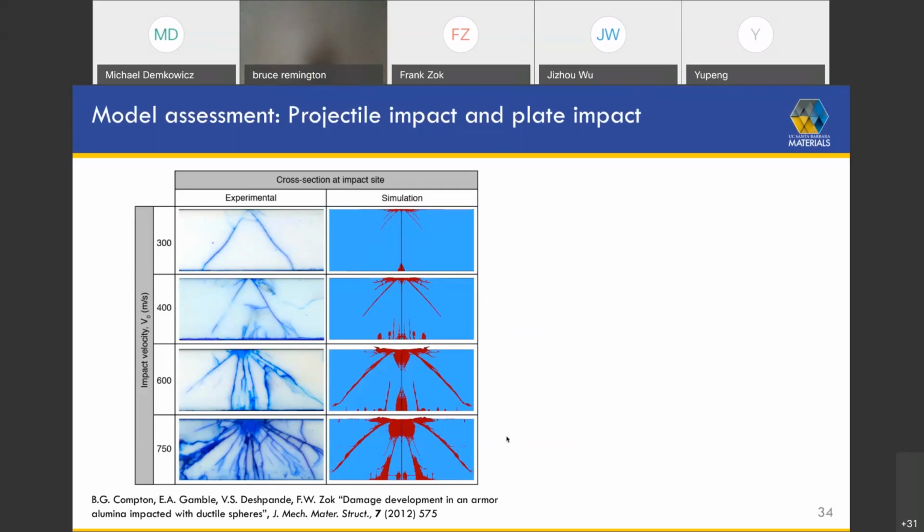I suppose it depends on what it is you want to study. I think there is interest in getting beyond the Hugoniot elastic limits and getting at shock speeds and the parameters and the equations of state. I think there could be interest in doing that for the purpose of studying phase transformations. Using flyer plate impact tests, you can indeed get to the pressures that are needed in order to induce those transformations.